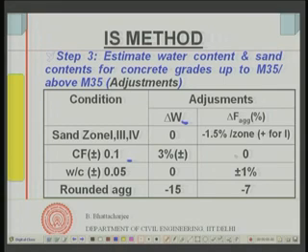And of course, compaction factor does not have anything to do with the sand content in the total aggregate content as per this codal requirement. Basically, the sand content would depend upon the packing characteristics of the aggregate system. So, the basic value that you have found out for zone 2 sand, if you change your compaction factor, it is assumed that it is not changed at all.